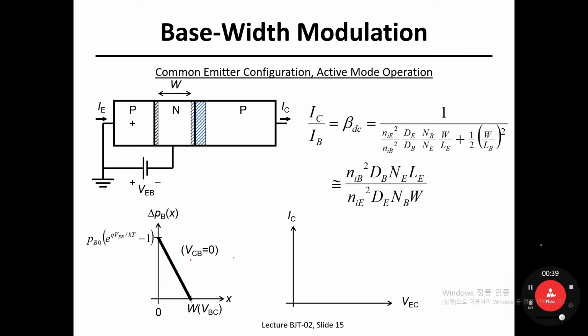maybe for the case of BJT. Okay, so the question is this: you know the short channel effect of MOSFET, right? As the physical dimension of channel length of MOSFET has been aggressively scaled down, the secondary effects or non-ideal effects originating from very aggressively scaled down channel lengths in MOSFET have become the main issue and main technical hurdle for the device engineers to overcome in the end.